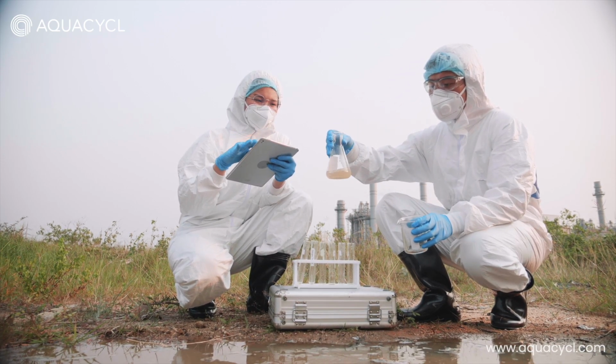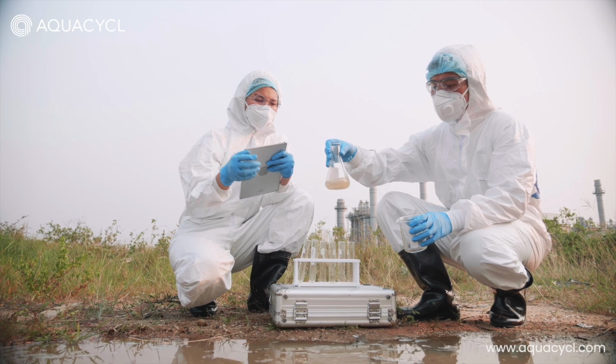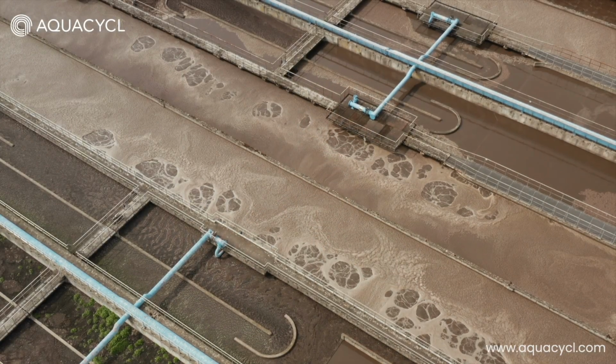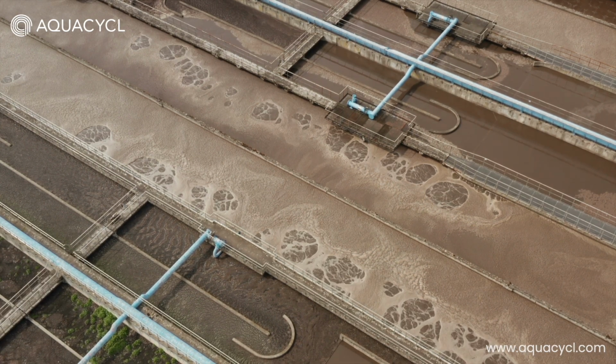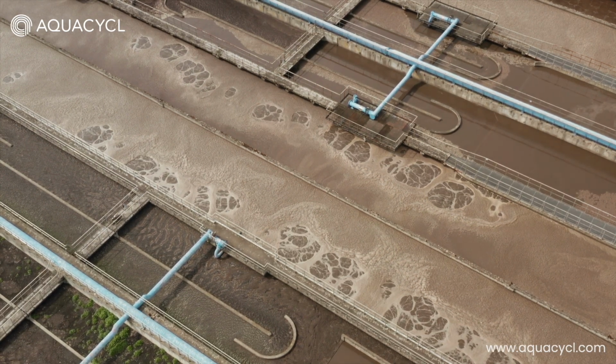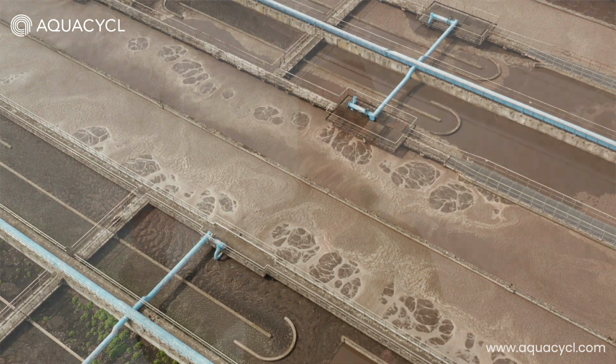And our bacteria, which are forming a biofilm and very robust and very active at breaking down total suspended solids, can actually address these lower organic but high TSS contents. So what that does, right, is minimizes the amount of total sludge that has to be dewatered and hauled, sometimes up to 30 to 50%. That could be a massive savings depending on how your facility is operating.